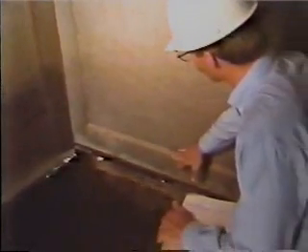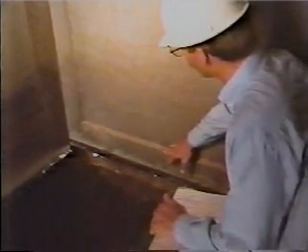Next, look at the gate stem and stem guides for corrosion, missing or loose parts, and scratches. The stem should also be straight and aligned properly with hoist and gate leaf. Now inspect the gate itself. On the downstream side, look for corrosion and structural defects in the gate leaf and frame, especially at the bottom. If the gate is in a conduit, check for cavitation damage downstream of the gate opening.